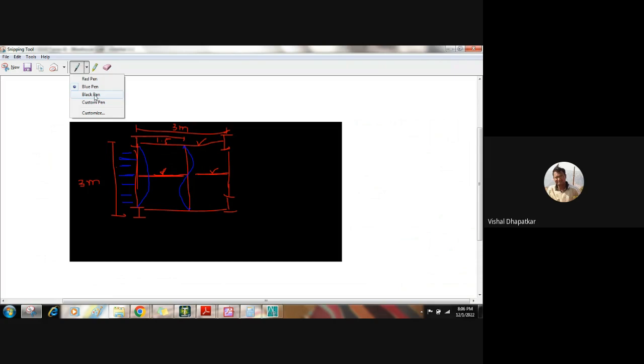चलो मैं बताता हूँ आपको। ये ऐसा भी नहीं बनेगा। ये जो बनेगा, ये भी ऐसा ही बनेगा। क्यों बनेगा? क्योंकि आप जब इस पे लोड लगाओगे, ये बेंड होगा, एक्शन फोर्स इसमें ट्रांसफर होगा, ये इसको बेंड करेगा, फिर से ये बेंड होगा, ये इसको फोर्स ट्रांसफर करेगा। When we want to transfer the force from beam to column, we need to have a bracing, राइट? ब्रेसिंग होगी तो ही ये फोर्स यहाँ से पीछे जाएगा कॉलम पे।